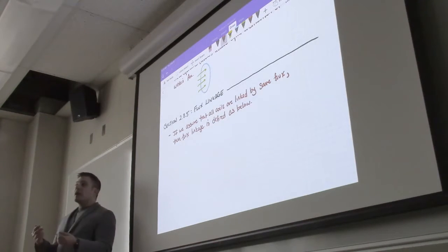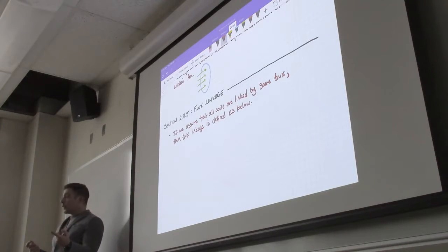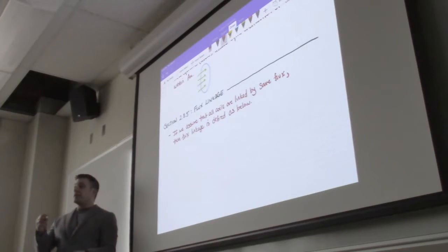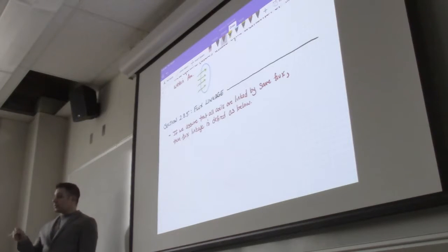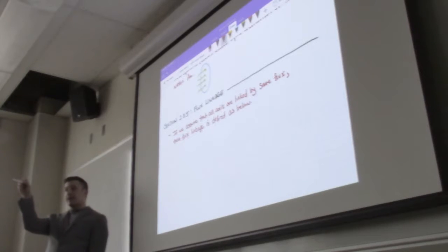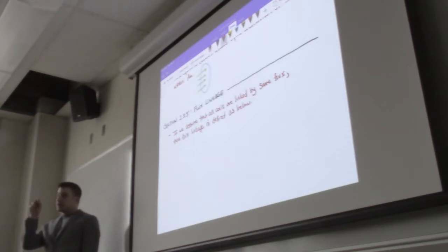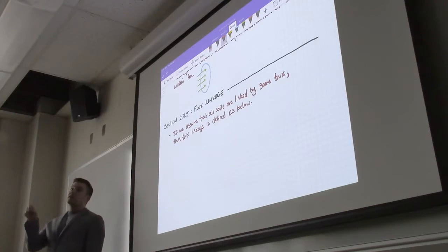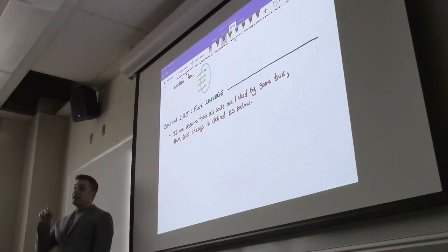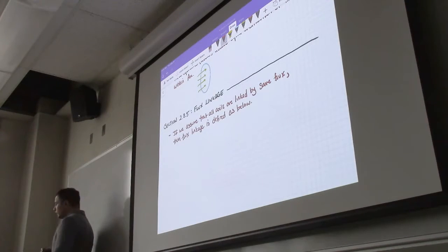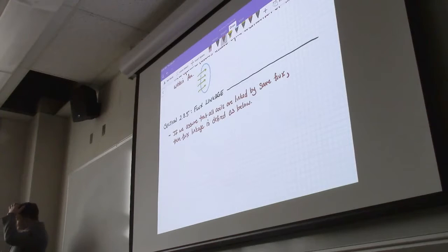And so that's a sort of intuitive way of understanding, okay, the effect of the coils are equal, right? The linkage is equal. Now, if we had unevenly spaced coils, or, I think what you were trying to say, we stuck one random coil in there between two others, like it's 1, 2, 3, 4, 5, 6, and we stuck a seventh one randomly in there, then that coil would experience a different flux relationship, or the flux flowing through that coil would be different than the others, potentially. And that, again, would make the math more difficult. So we're assuming that they are all linked by the same flux.